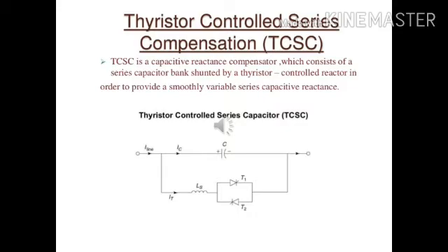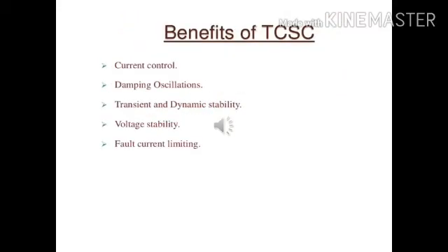On the other hand, while acting as an inductor, it absorbs the reactive power and eliminates the overvoltage condition, right? Okay, these are the benefits of a TCSC I listed out. Along with that, we can say that it has fast response, is simple, and generates less harmonics.